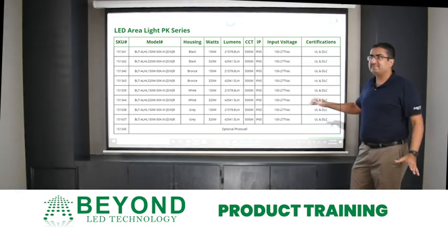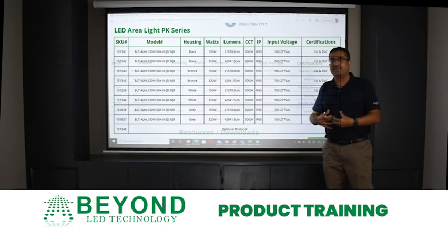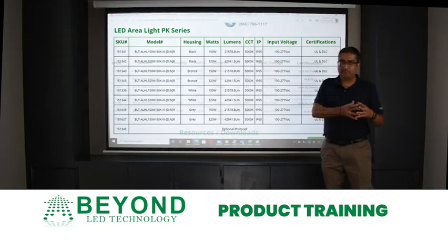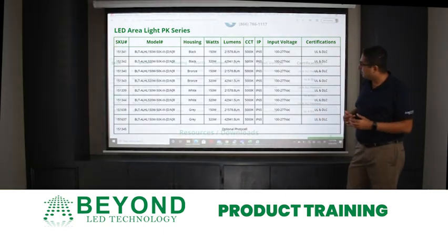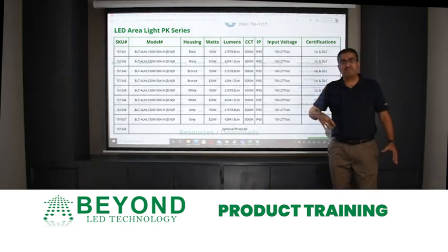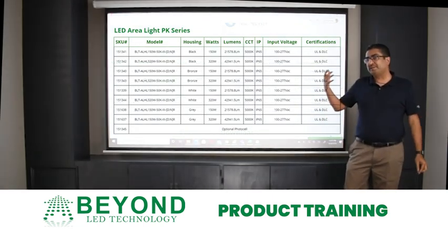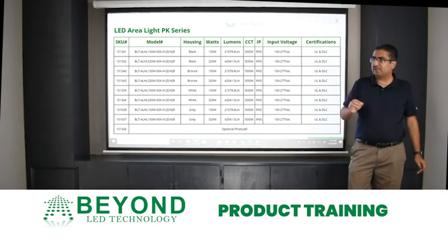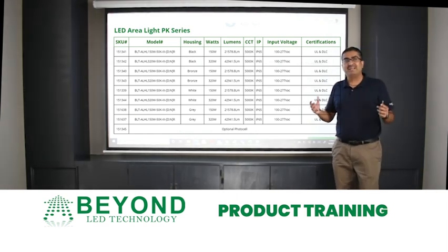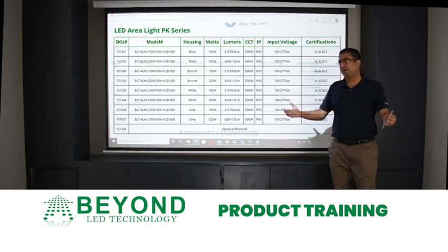We talked about the DLC certification, which is required to get rebates from a lot of power companies. Now, we also talked about the LM79 report, which is the testing report for the entire product. We talked about the LM80 report, which is for the chip only. And we also talked about the IES file, which is required to generate a photometric report for the project.